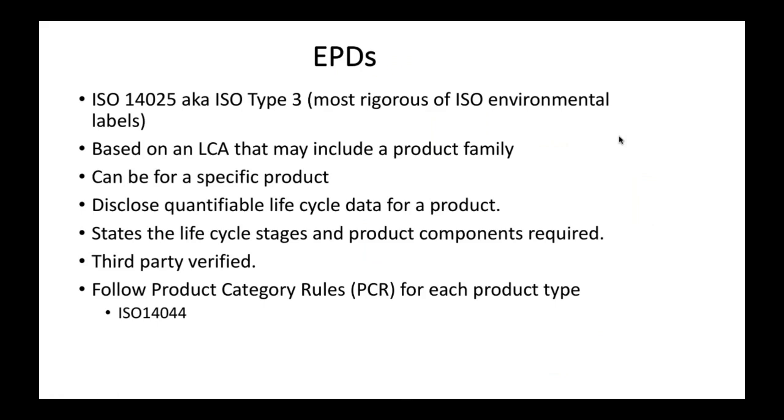Great. So to continue a little bit on EPDs, I will say that EPDs can be for a specific product. You did see in that LEED credit that there are a couple of different types of EPDs, one of which is an industry-wide EPD, which I would definitely recommend looking into to see if something that you are already making has an industry-wide level EPD. This is not counted for as much of a point as a product-specific EPD, which I'll explain in a moment.